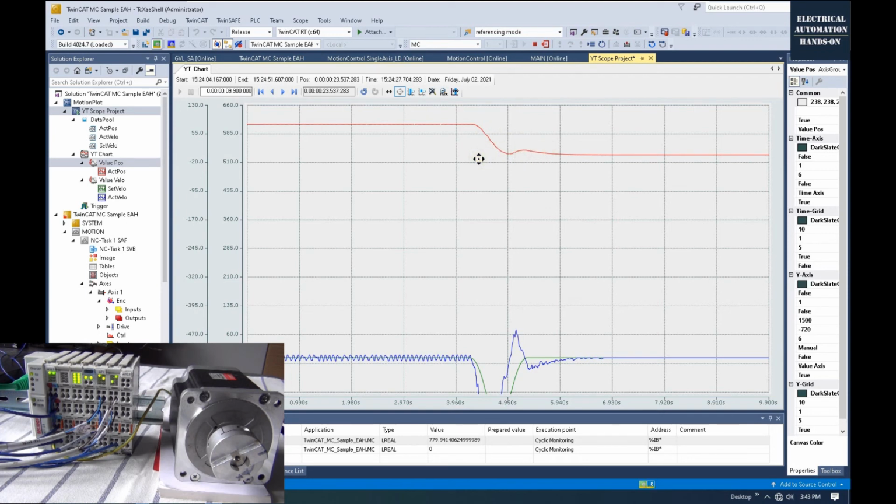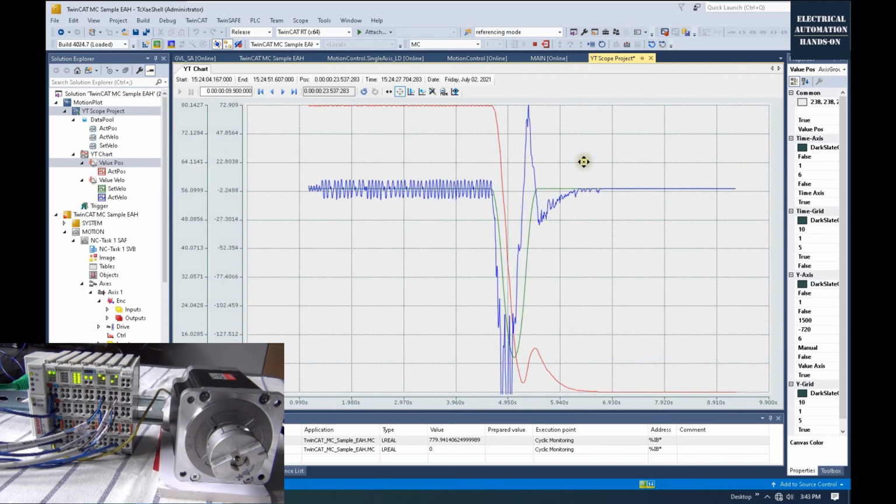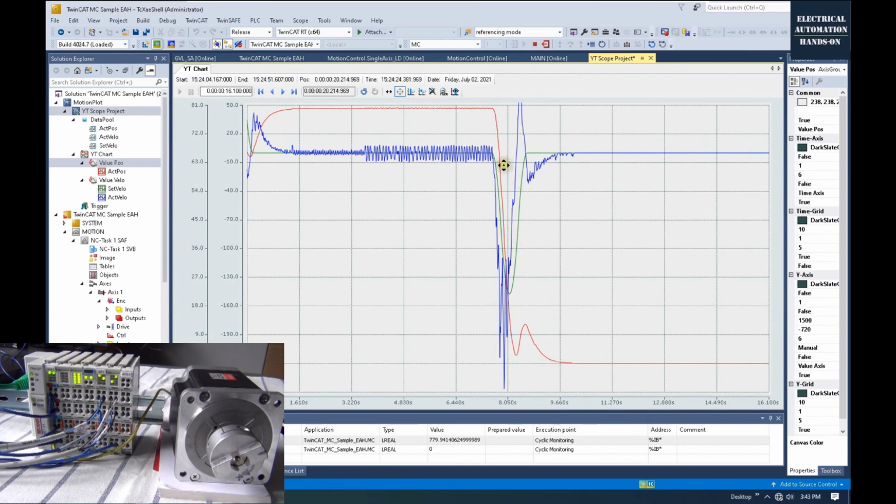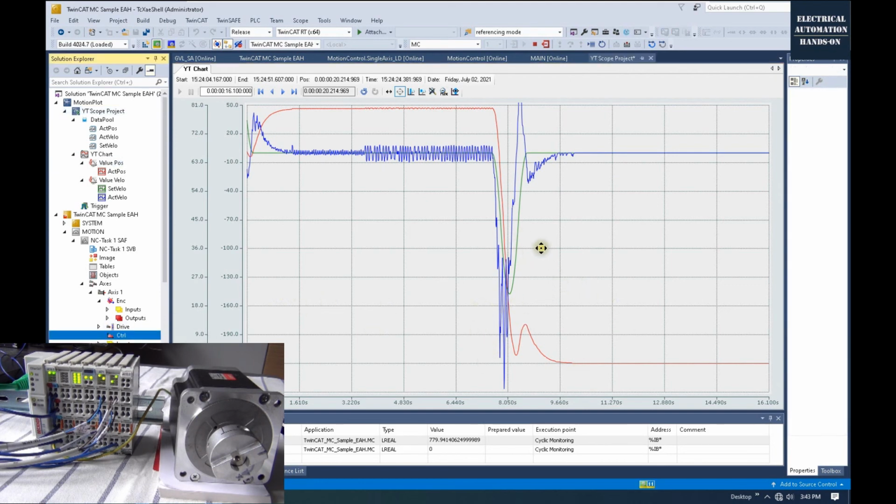That means the mechanical parts will move to the target, then go back a little bit, and then go to this position again. It will show hesitation and vibrating there, right? Especially in this case, we can see it go there, go back, and then adjust the axis, right? So this curve can also be used to optimize our parameters. For example, if this is the first time we see this happen, that means we need to optimize our axis.